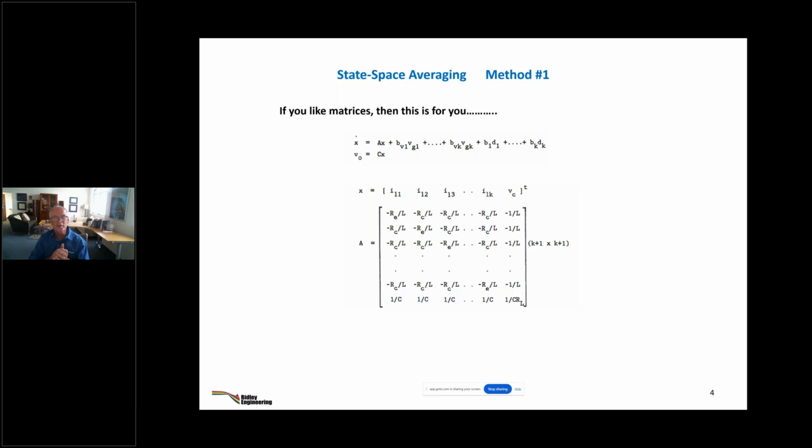And then what you have to do in state space averaging is take the (sI - A) inverse matrix and invert that by hand to generate all the equations that you're going to need for the converter. So this was tough work, but if you've just come out of college, it's like, oh, I can invert that matrix, that's no problem. So that kept us all going with equations and curves for a while.